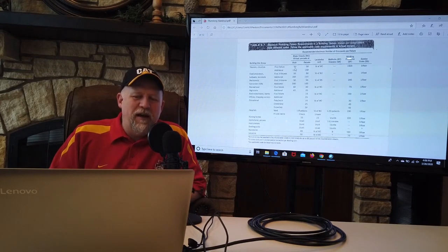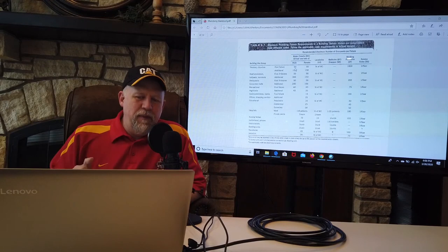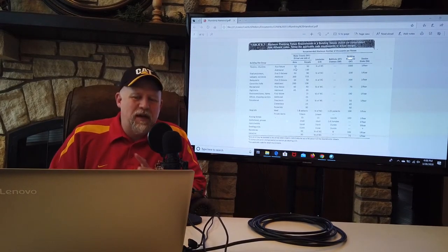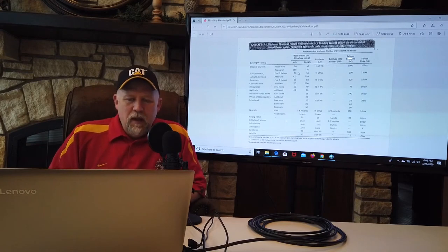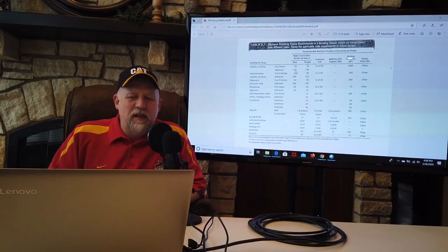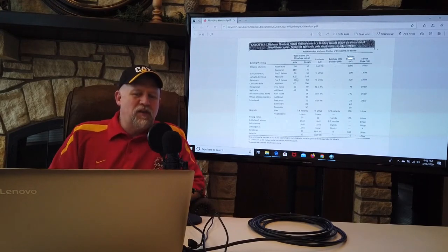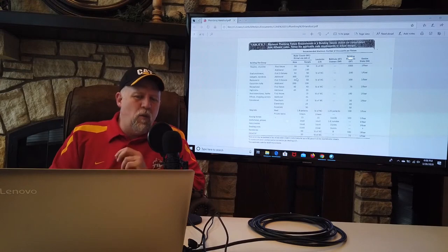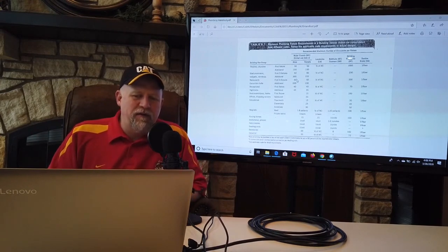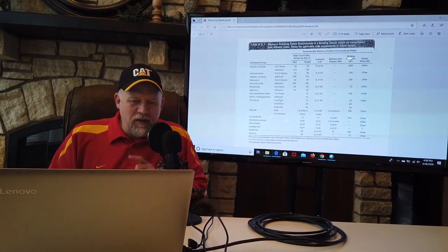So notice, if I have 1 to 50 people, and notice this is split up male and female occupants. I'm going to talk about that one in just a second. But once you know the number of people, you say, all right, the first fixture can handle 50, and every additional fixture is another 150 people. So as soon as I have 201 people, I need a third water closet, and it goes up by 150 after that. All right, notice how different it is for, say, offices.